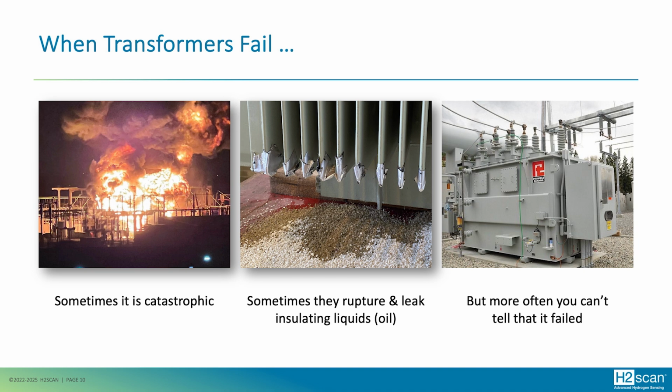But the truth is, it's sometimes catastrophic. Sometimes they just plain rupture. They leak insulating liquids. And sometimes, please forgive me if I call it oil. I'm somewhat in the old school. So if you hear me talk about oil, I mean the insulating liquids of the various forms. But more often than not, you couldn't tell. You can stand next to that transformer. It'll look as good as it did the day you installed it, and you wouldn't know that it's failed.